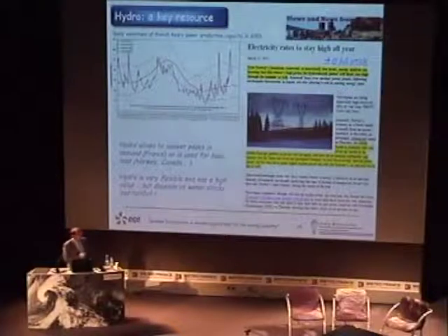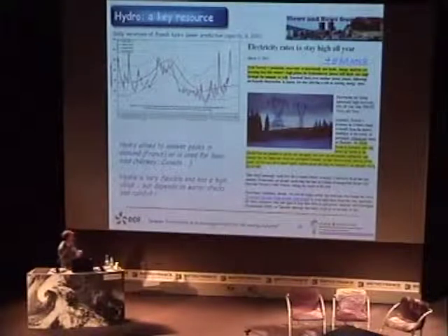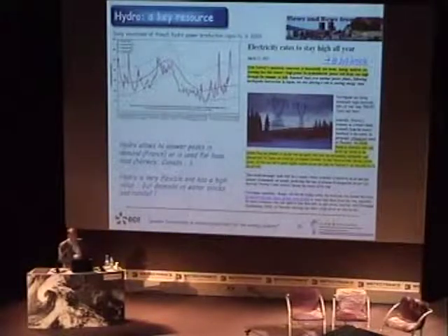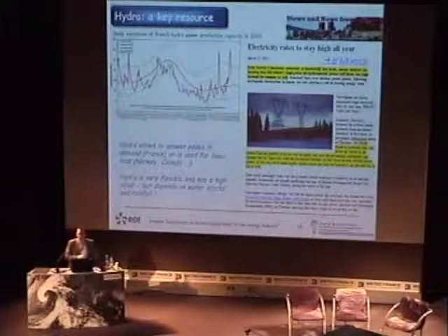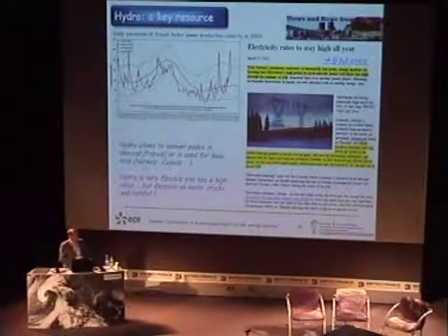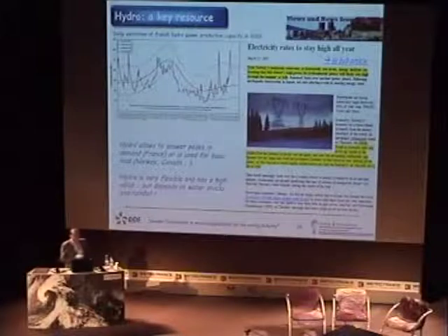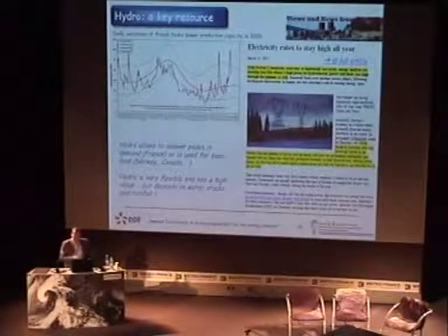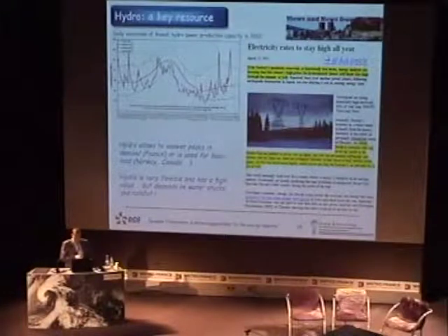So the first thing you can see is that we have quite a large internal variability in hydropower production capacity. We also have a strong seasonal cycle with, of course, water incomes mainly in spring with the melting of snow in the mountains and with precipitations in the winter. And the red curve is the one for the particular year of 2003, where we had a strong heat wave in the summer in Europe. And you can see that in addition to the internal and seasonal variability, we can have a very, very strong day-to-day variability. And so this is quite difficult to forecast, and a reduction in the uncertainty of this kind of data is very, very important.